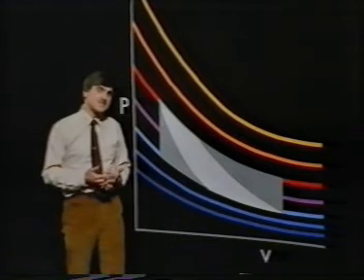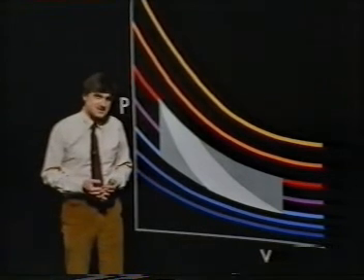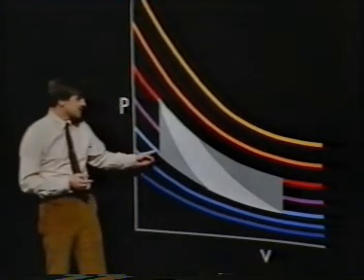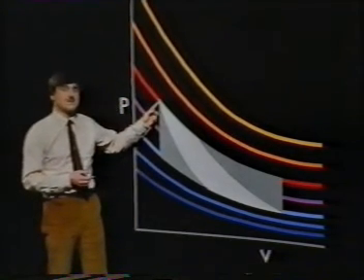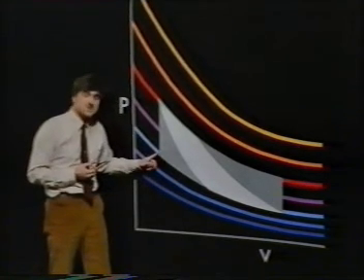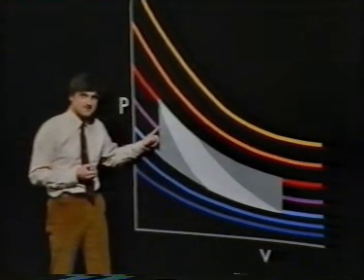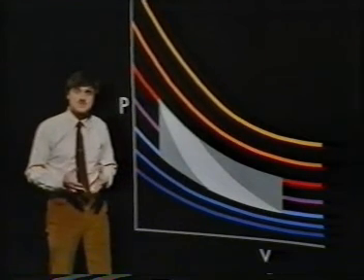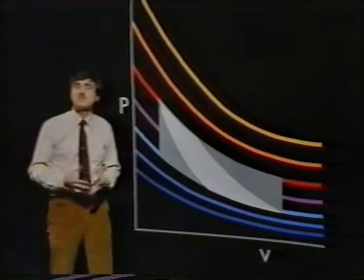But is the Stirling cycle as thermally efficient as the Carnot cycle? Well, no. Because during these constant volume processes, energy transfer by heating occurs while the temperature of the working fluid changes. And we've seen already that that is an inherently irreversible process and therefore causes a drop in thermal efficiency.